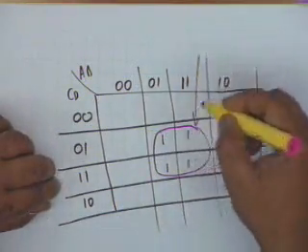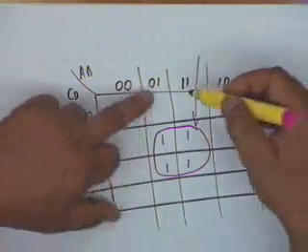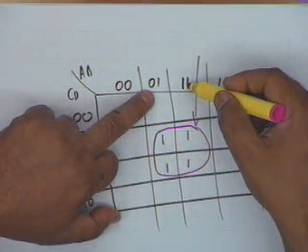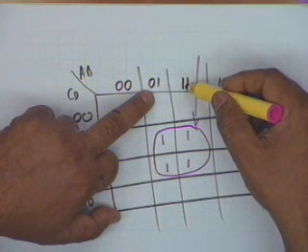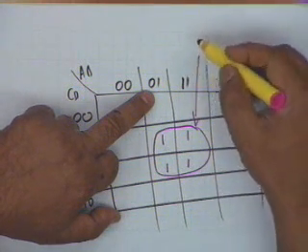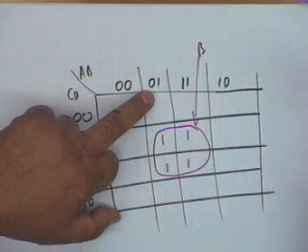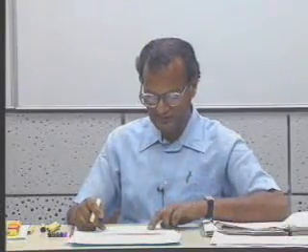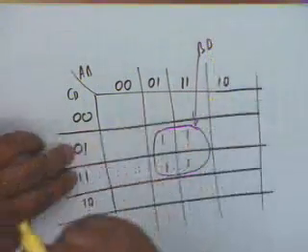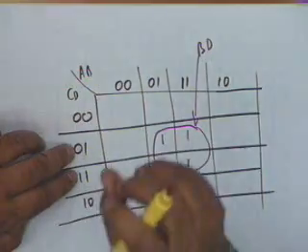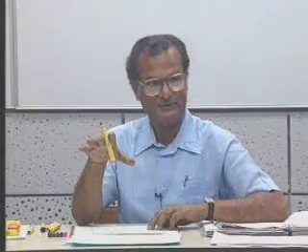The expression corresponding to this, you see, 0 1 1 1. A has changed. Therefore, it should be independent of A. It should have a B. Here 0 1 1 1, what has changed? C has changed, therefore this simply represents BD, and it is a tremendous simplification.